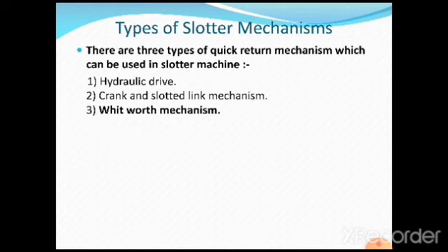Now let us understand the classification. Slotting machines are classified based on the mechanisms used: the hydraulic drive, the crank and slotted link mechanism, and the Whitworth motion mechanism. These drives are used depending upon the application and the characteristics of the job to be machined.